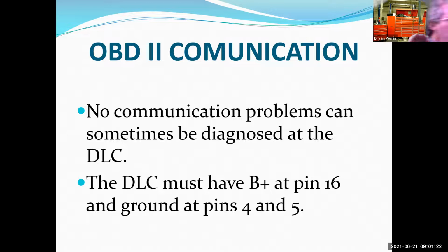Also, your connector on your tool, if you look at the pins on it, and it has the 16 pins, 2 of them are supposed to be longer. The 2 longer pins are for 4 and 5. And that actually came from BMW out of the SAE stuff, because they wanted ground connected first before all the other pins were connected, and they wanted ground disconnected last after all the other pins were disconnected.